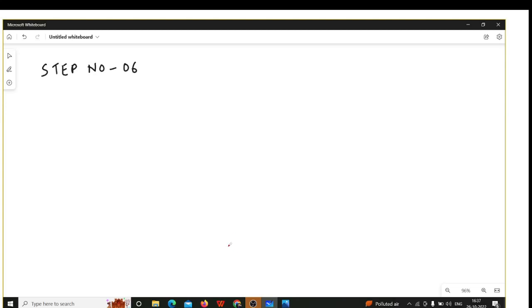In this video, we will discuss the further part of the footing. Already we have discussed the design of the footing up to step number 5, where we discussed how to find the depth of the footing. We have three criteria by which we have to finalize the depth of the footing. Number 1 is the bending moment, number 2 is one-way shear, and the third one is two-way shear. Whatever depth of the footing we provide has to satisfy all these three criteria. So the further part will be taken in this video.